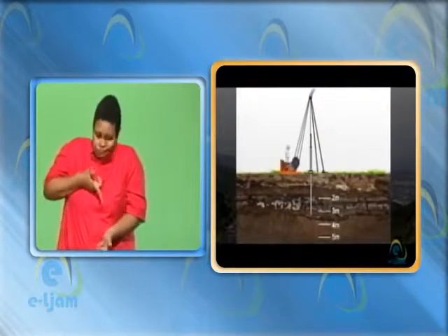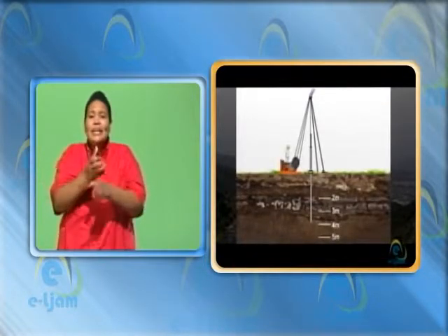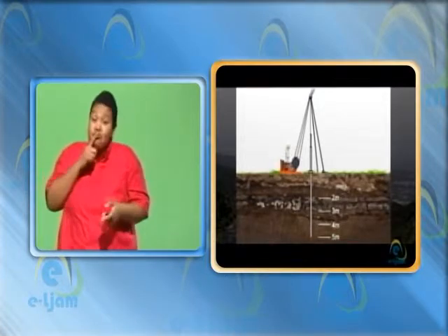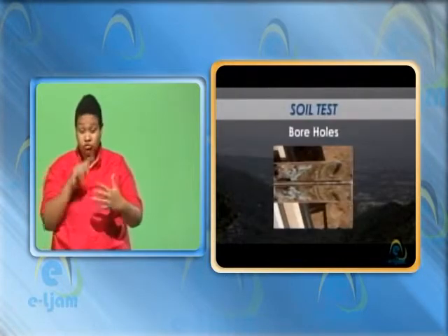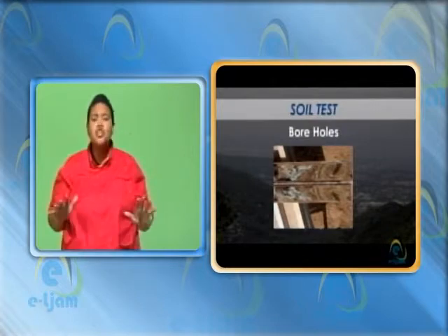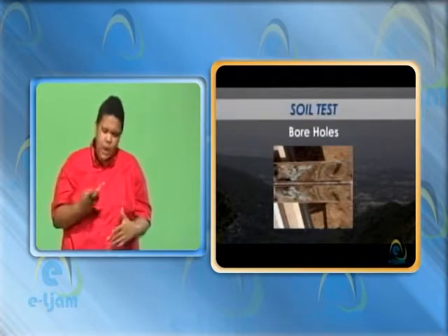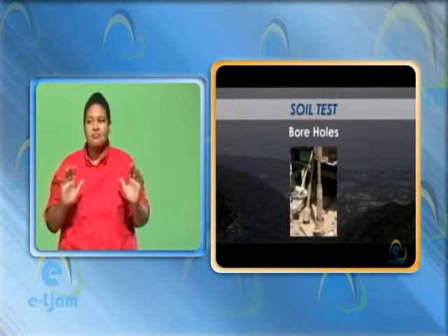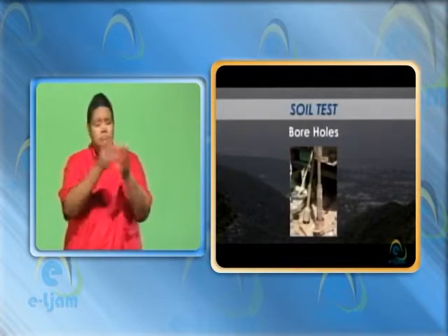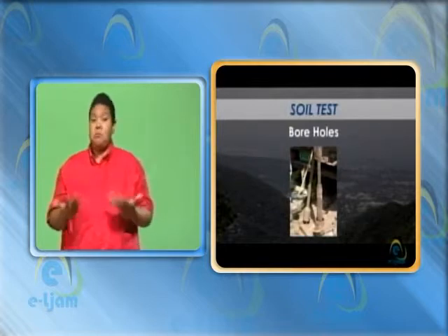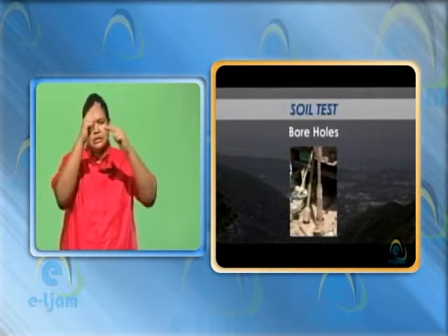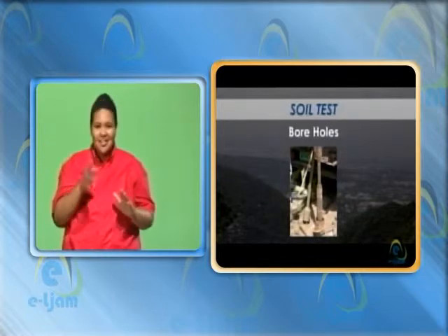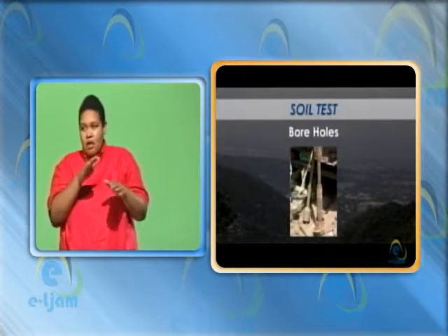Where it is necessary to obtain samples beyond a depth of 2 meters, drilling is carried out by machines. The samples are collected as drilling progresses, and depths at which samples are collected are noted. These activities will also help determine any difficulties which may arise during the construction process, for example, the depth of the water table, or if timbering will be needed.